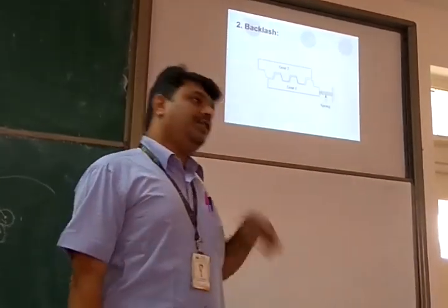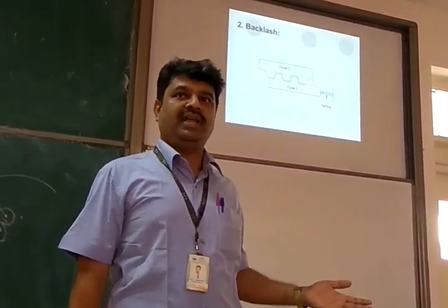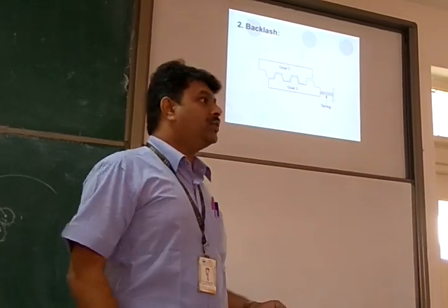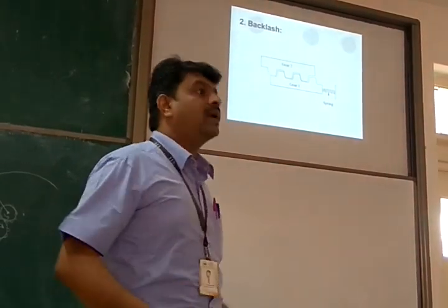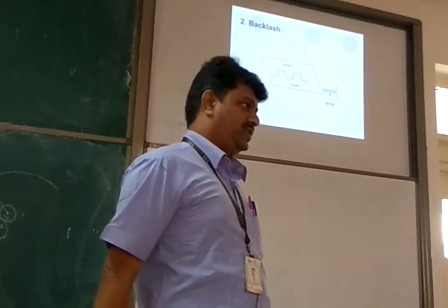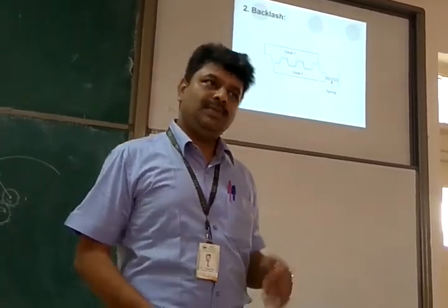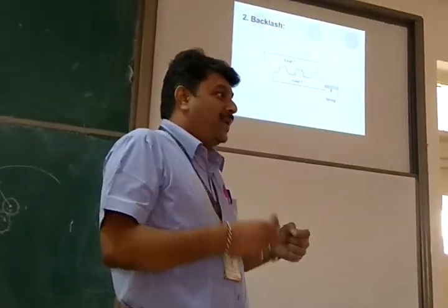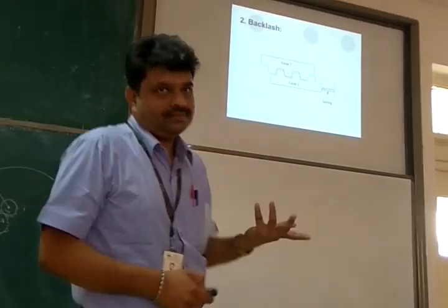But a light spring will introduce another problem, a loading effect, because in order to show a reading, you have to overcome the light spring force. That's another problem. That's why you make it as light as possible, but it must still do this function.